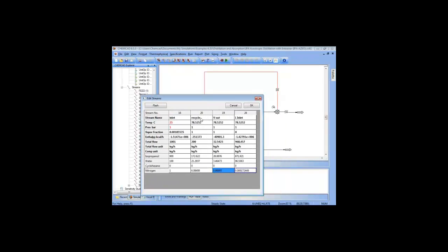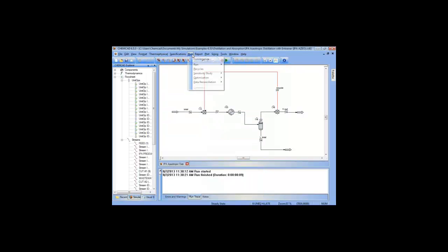If we have only isopropanol and water, that's fine, the isopropanol and water mass balance. But we have a very small amount of a different chemical, the nitrogen. So I'd like ChemCAD to be more precise. I would like ChemCAD to perform 2.00 plus 2.00 equals 4.001. I'd like ChemCAD to give me an answer like that and accept it. I don't want ChemCAD to say 2 plus 2 equals 4.3. I don't want it to accept that as converged. So I need to tell ChemCAD, be more precise with the answer you're looking for on this simulation.